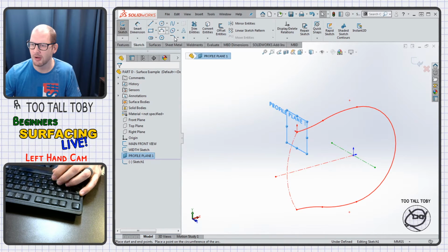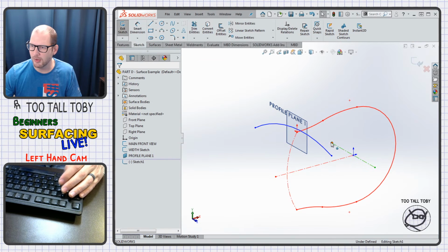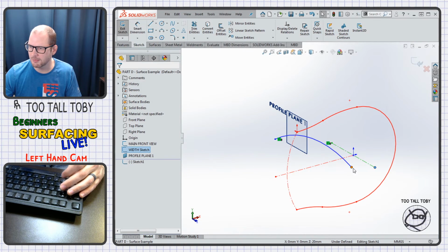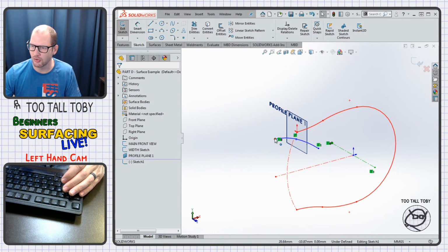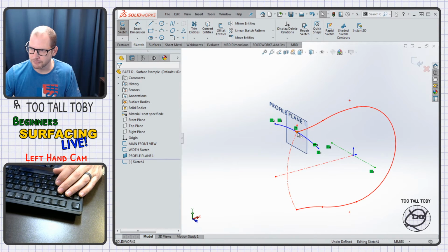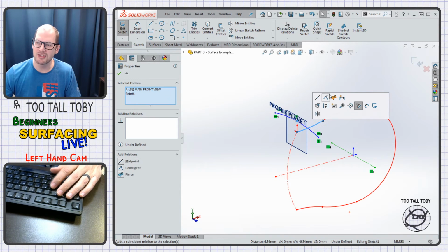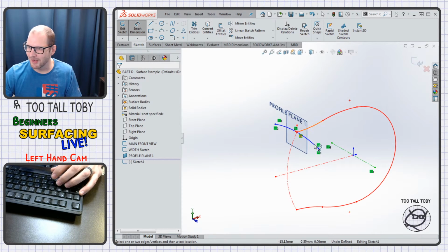I'm going to orient my view, and I'm going to create a 3-point arc here. I'll say that I want this point to be vertical to my layout sketch. A lot of these shortcuts that I'm using here are in my Power Moves videos, like knowing how to hold control and let go of control. Go here horizontally. A lot of times when I'm teaching essentials, I tell people that we learn all about relationships and letting go of control. And they think I'm weird.